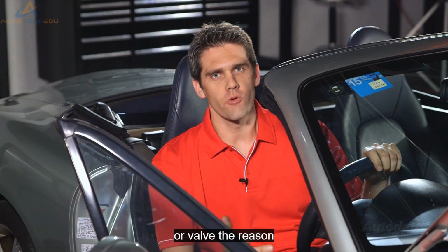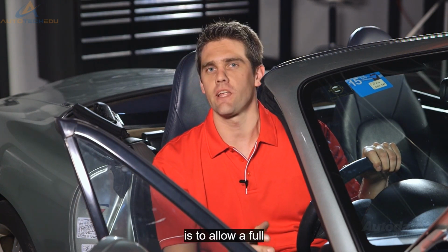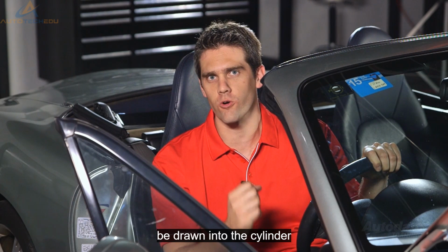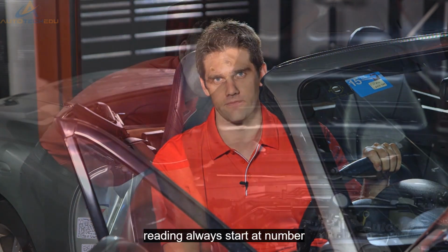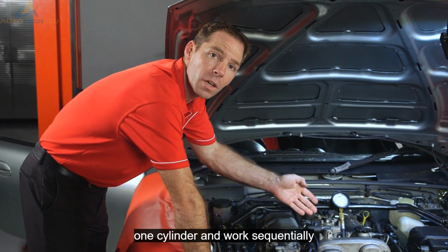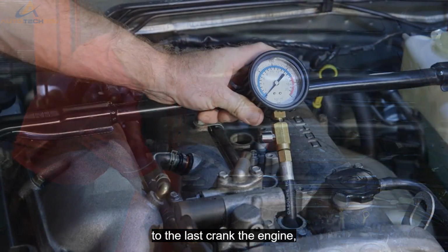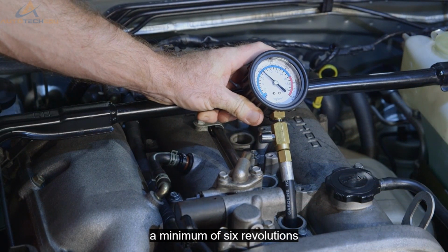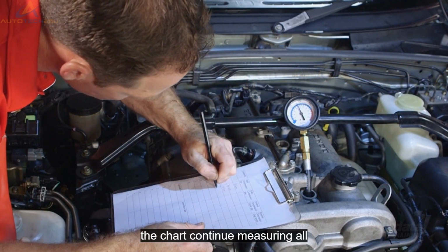The reason for holding the throttle butterfly in the wide open position is to allow a full charge of air to be drawn into the cylinder. This guarantees an accurate reading. Always start at number 1 cylinder and work sequentially to the last. Crank the engine a minimum of 6 revolutions or until the needle stops rising. Record the result on the chart.